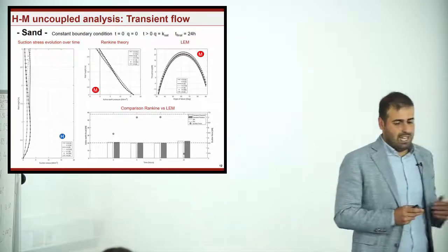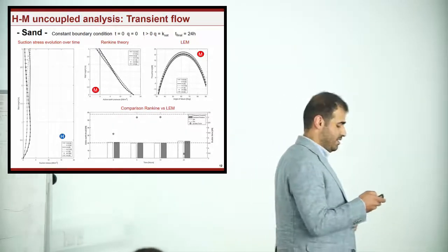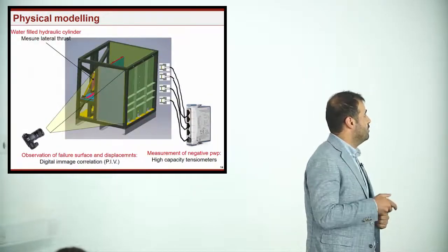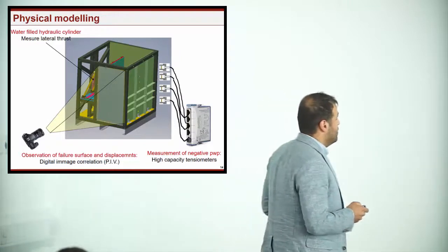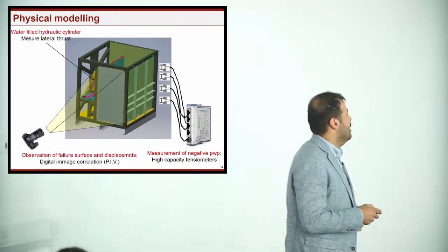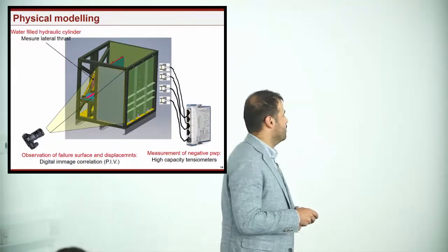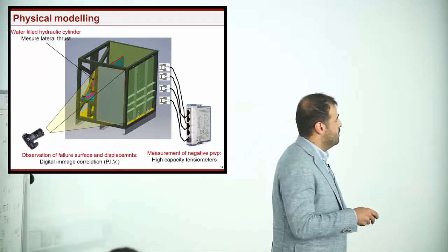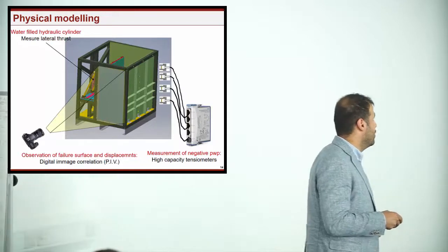Of course, behind this problem there are some limitations. There is no experimental validation. For this reason, we started to model this phenomenon in the laboratory with a physical model. This is the model that has been designed and built at the Laboratory for Soil Mechanics. It's a fully equipped model, with high capacity tensiometers for the measuring of matric suction.